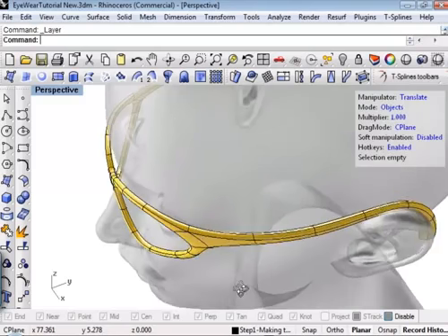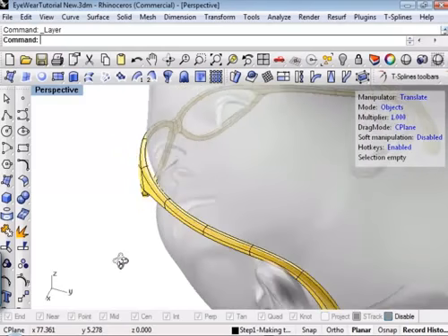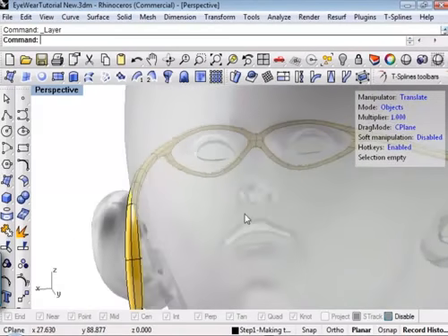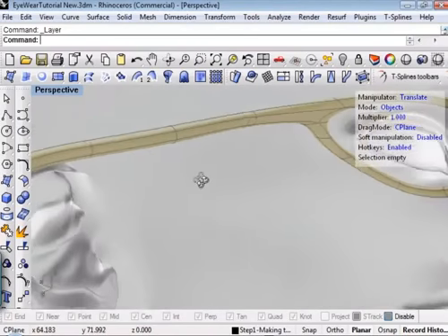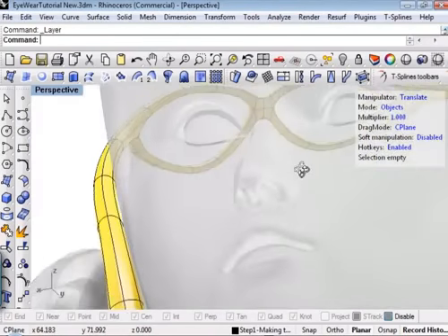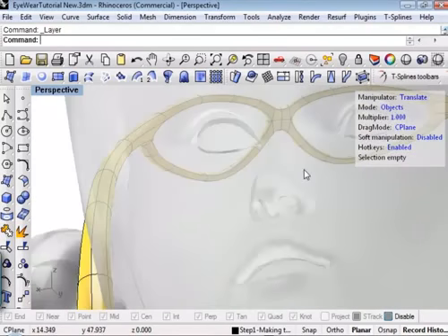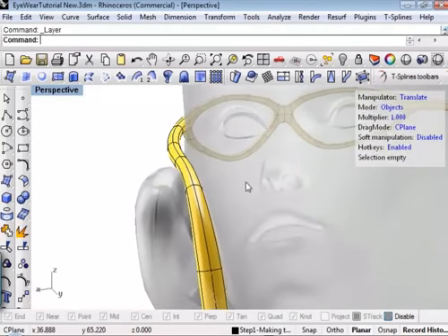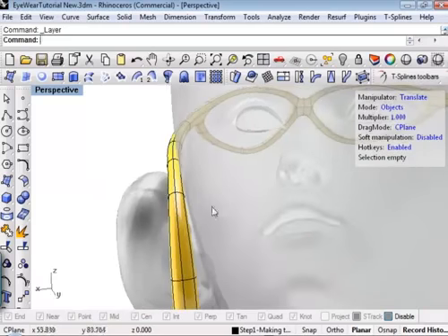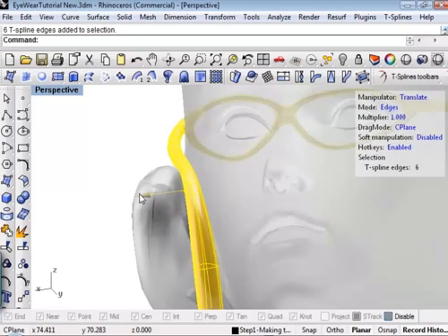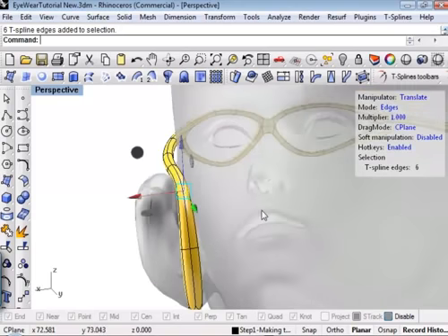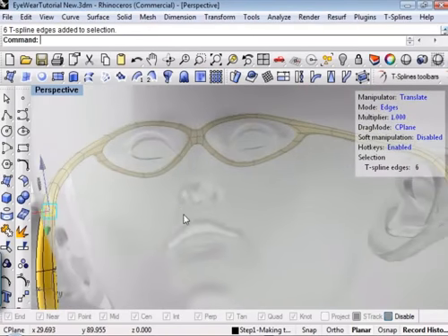At this point, I can look at my model and evaluate it, let me just go inside the model here and see where there's any fit issues. So you'll notice that it doesn't look like I'm colliding anywhere, but maybe I need to improve my fit a little that it's touching the head. So I'll grab an edge, and I'll just slide this in a little bit. And if I zoom out a little bit, you can see that that's actually adjusting on both sides.